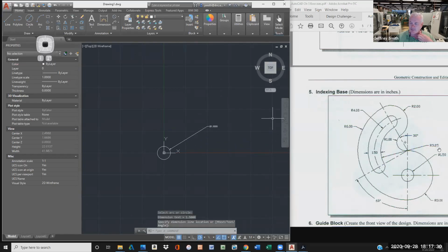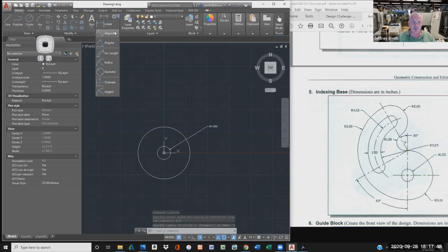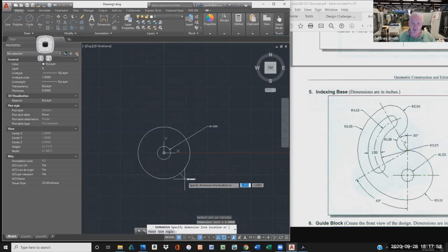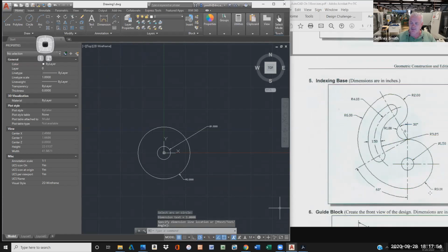Now I'll go ahead and make this circle here. I'm going to make another one. It tells me it's a radius, so just to keep my brain functioning properly, I'll type in 0, 0, and then so I don't err, I'll just type in 3. So I'll probably want to check that. And if you notice, when I check these dimensions, I try to do it in a manner that replicates the drawing. I'll go back in and change the tolerances later. So I've got this bottom done.